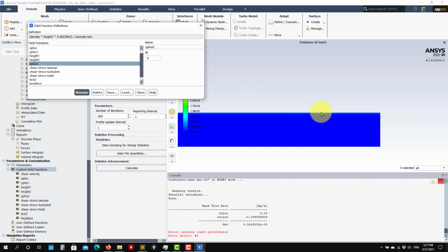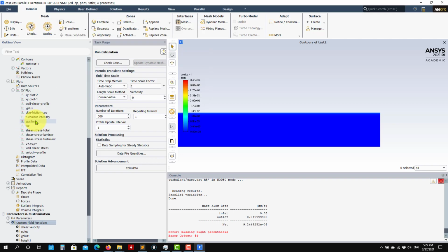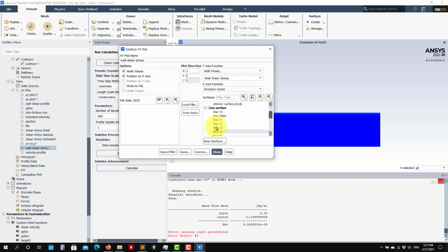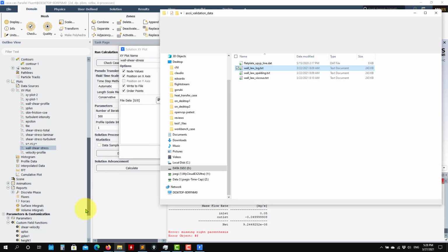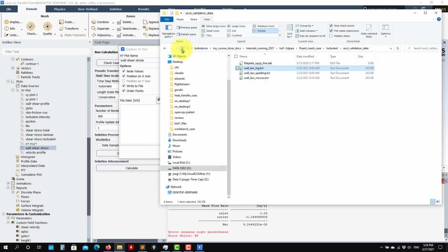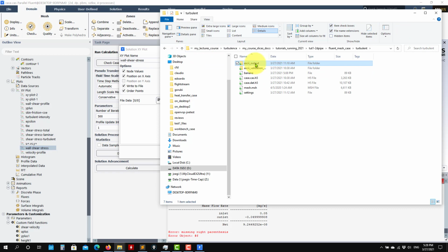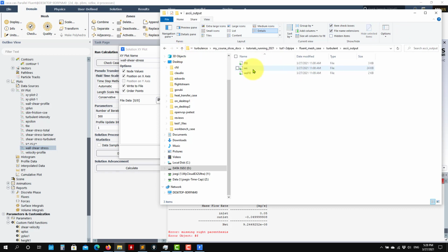Density times height times the shear velocity at that point. So remember that I'm doing this sampling at 6.9. So at 6.9, I know my wall shear stress. So how do I know that wall shear stress? Well, what I did is that, for instance, two ways. So you can get here in this monitor. So see that I, in line 10, write that information. So there in your files, okay, ASCII out, I already put the output here, but for instance, I already saved that information there.